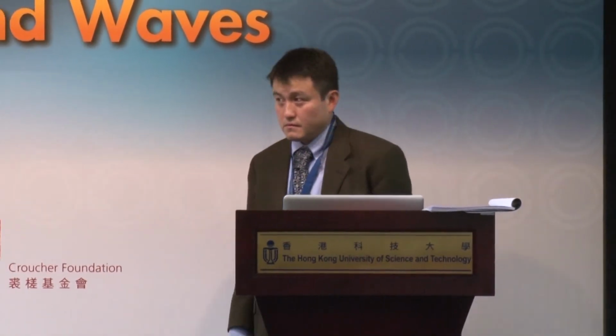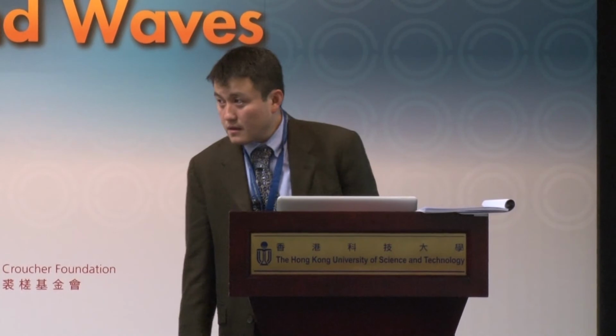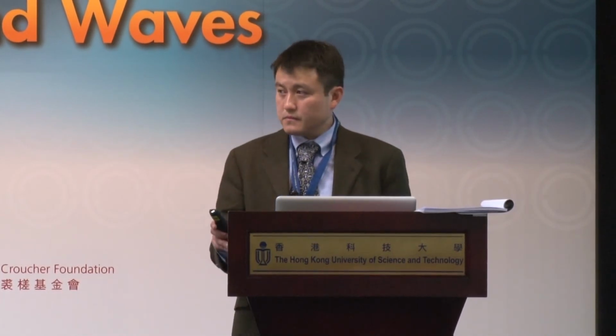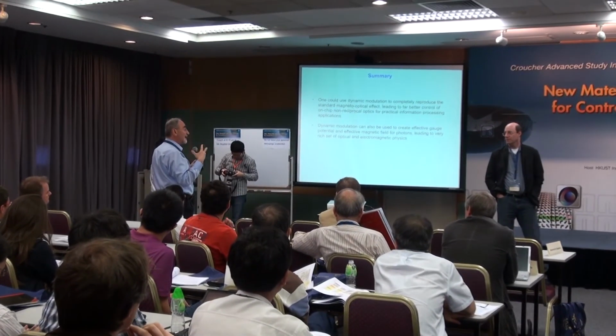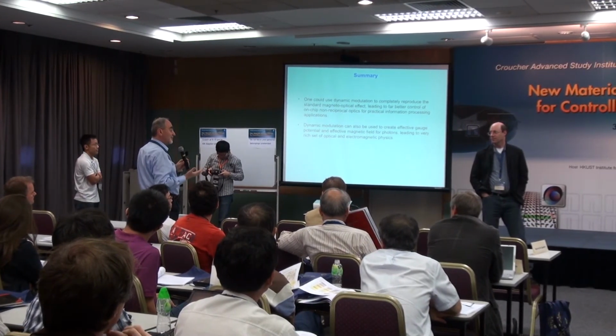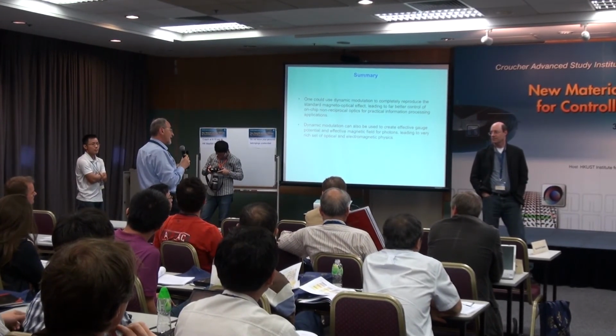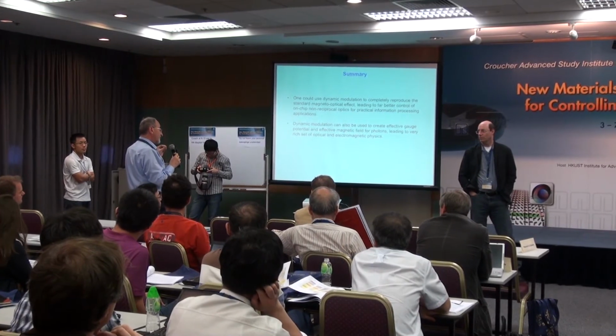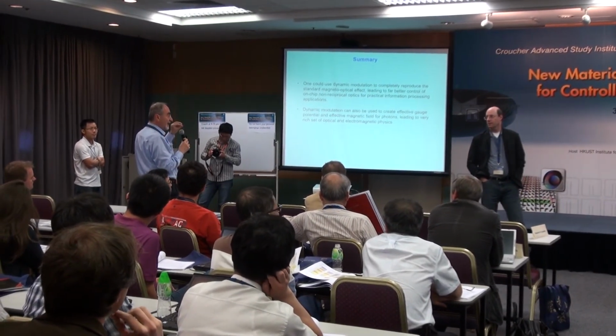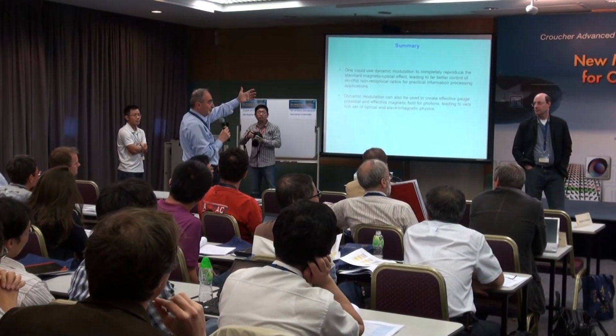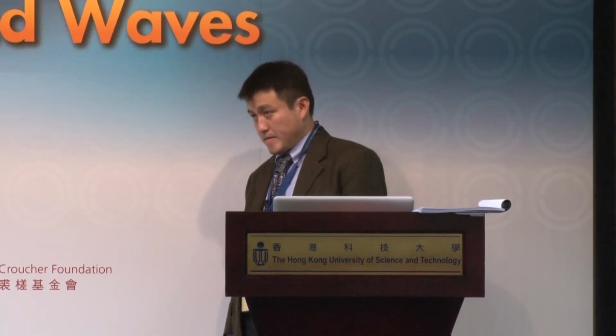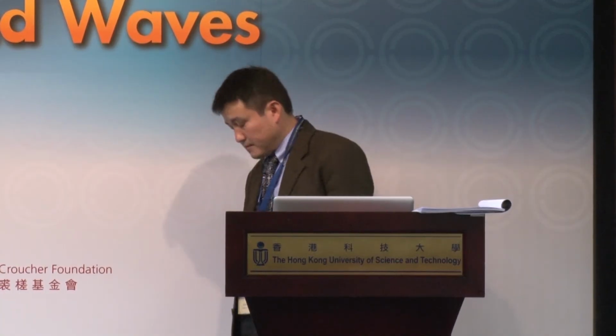It's just fascinating. I want to talk with you in the break some more. But I'll bring up the point about how magneto-optic isolators are used in real systems. The purpose of the magneto-optic isolator is to prevent the laser from getting feedback from some reflectance way down the fiber that's completely out of control.